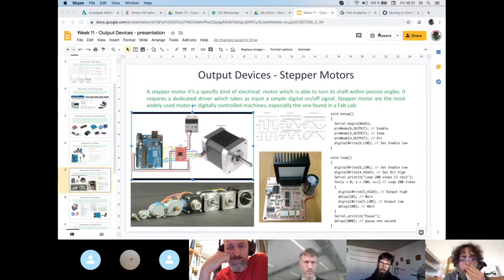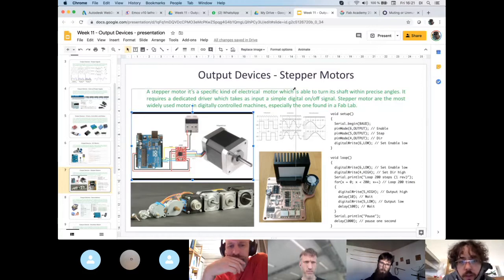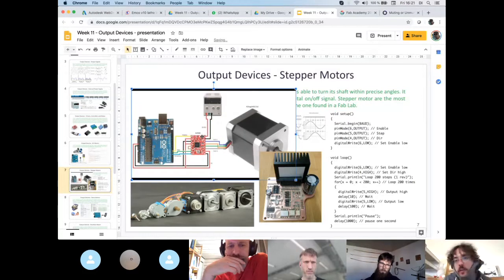So the capacitors here, guys, also there are some little ones, there is also a little one over here. It depends on the size of the driver and the motor and so on. It uses one of the main features of capacitors, which is to give you a boost of current at the start of the motor. Whenever you need to start the motor again, you may need a peak of current that the driver cannot give you immediately.